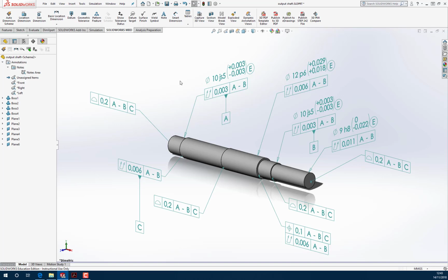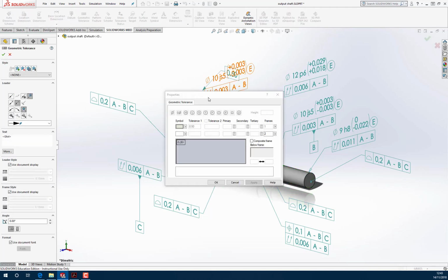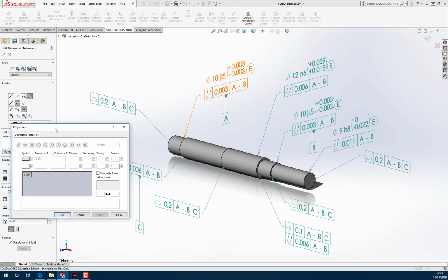That's our basic view of all the surfaces that we've created so far controlled, and we can test to make sure they're all fully controlled. Aha, we've got one missing. I can try to show what this is. So geometric tolerance, and this is the surface that isn't doing anything essentially other than providing bulk support for that bearing face here. So profile of surface.